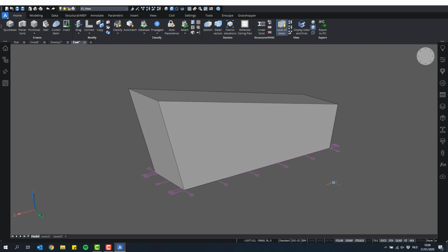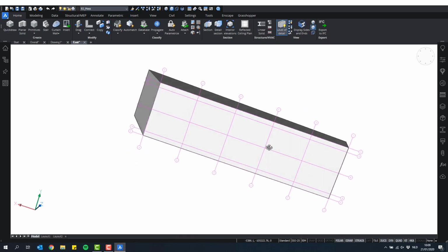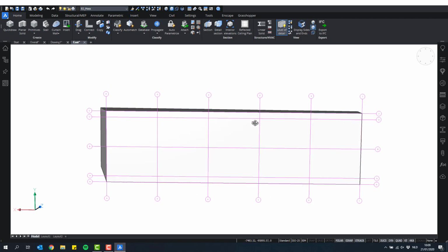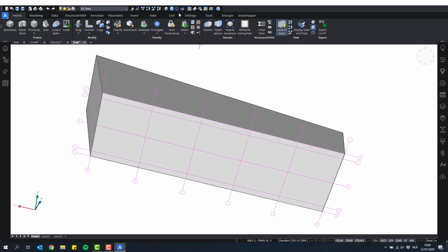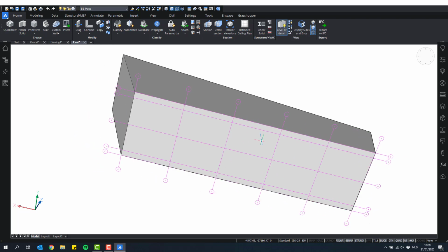There's, again, 100 ways to model this, but actually in this case, I'm going to use this predefined grid here. The method I'm going to use now is kind of convoluted, and normally you wouldn't use this method, but actually it's one of the easiest to learn in this case, so I will just use this one. What I'm going to do is enable my face detection. Oh, sorry, my boundary detection. And you see now, because there is a grid on top of this bottom face of this building, when I move my cursor inside one of those grid cells, the boundary is detected within this grid cell. The boundary on top of this solid face.